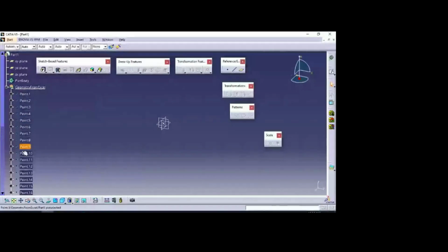Now you can see the box moving down. That means it is importing. Now if you open that minimized Catia, you can see all those points. The geometry from the Excel is imported. To see it, since it is like a small point, you know how to make it bigger using the fit all in tool from the view toolbar. Now the airfoil is imported.